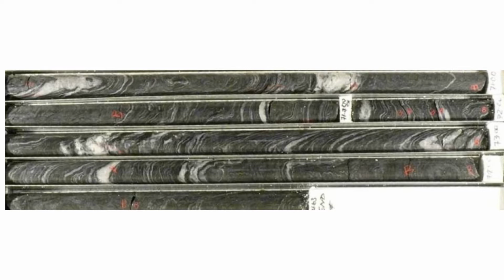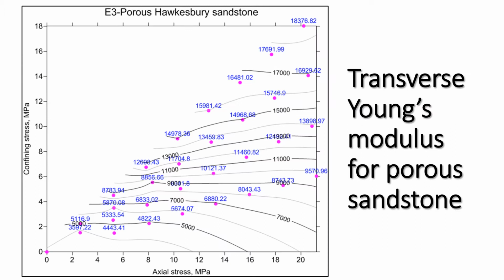If the rock is anisotropic but linear elastic, then analysis is possible and simple provided that the anisotropy is axis symmetric with the core. If the anisotropy is not aligned with the core, its analysis is possible but more complex. Many rock types are non-linearly elastic, and the Young's moduli and Poisson's ratios depend on the state of stress. If the rock does not behave in an elastic manner, then overcoring is not a suitable rock stress measurement system.